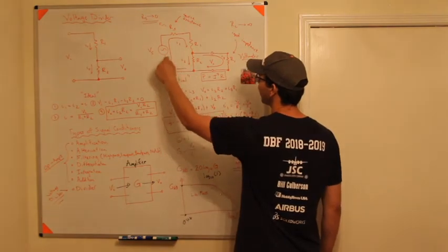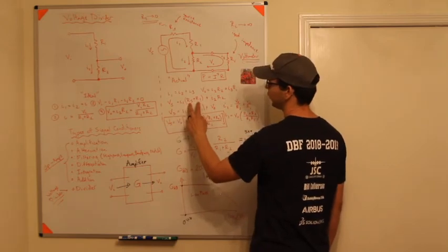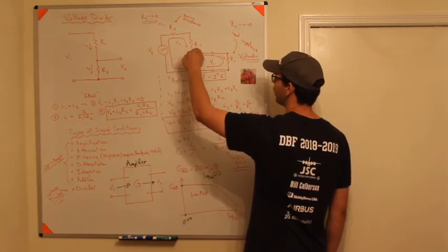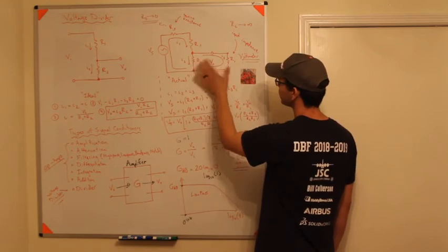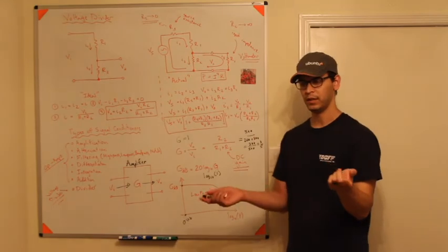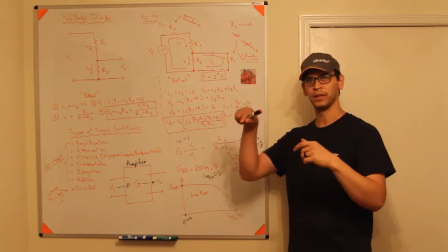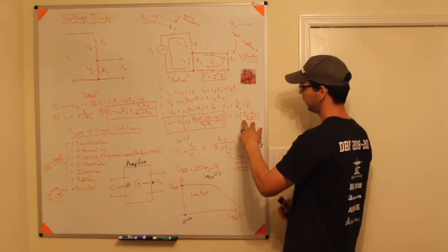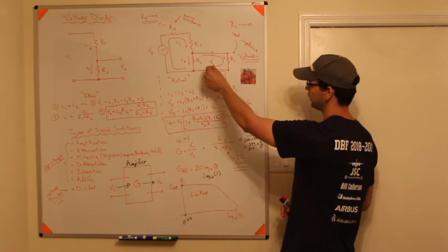So this gets a little bit more complicated. Now you've got current I1 running through here, so you have the same current running through RS and R1. So that means RS and R1 are in series, you can add those together. But then you have a situation where part of the current goes through I3 and part of the current goes through I2, but these two resistors are in parallel, and so you can add those resistances together using the parallel rule, which I think is 1 over R plus 1 over R all raised to the minus 1, I'm pretty sure. And I did the math to just kind of do it. I don't like to memorize formulas. But anyway, you get this relationship here for the two resistances.